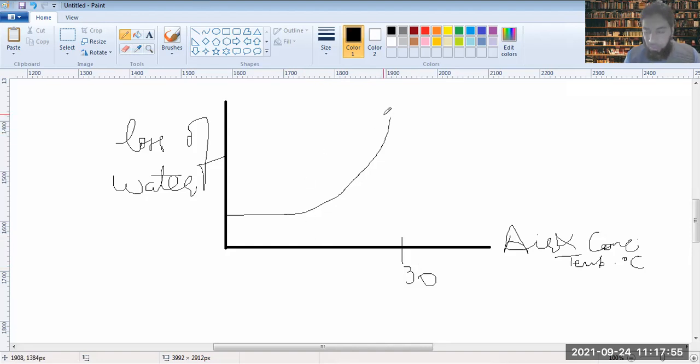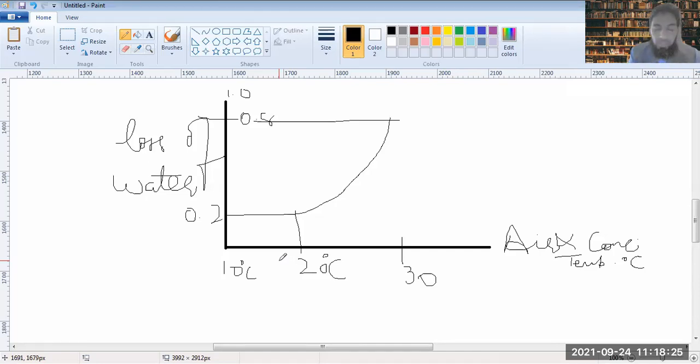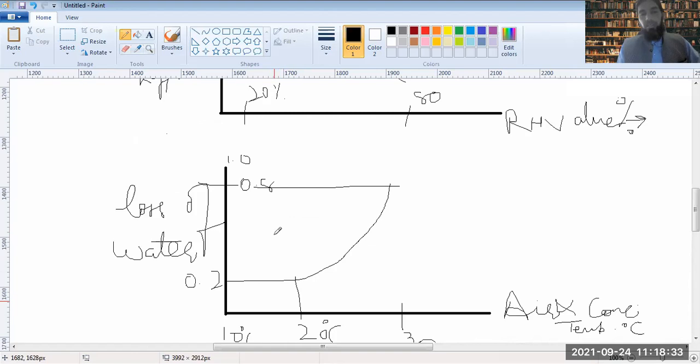be almost 80% of the maximum that it could happen. And this is just at 20 degrees Celsius. The loss of water is just 20% of the maximum. And still at 10 degrees Celsius, it is still the same. So there is hardly any difference here between 10 and 20 degrees Celsius. So the ideal temperature always for concreting as well as for curing is 10 to 20 degrees Celsius. And 15 degrees Celsius, which is the room temperature, is always considered to be the ideal temperature for concreting.